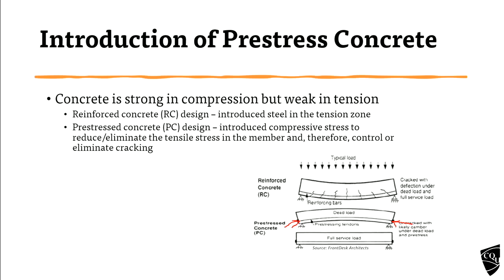You can see while the bottom part compresses a little bit, the top part will bend upward, so the overall beam will bend upward. At the moment this is construction time, so we don't have any loads on the beam, but we apply the compressive force, so the beam will bend upward.